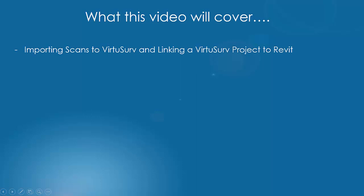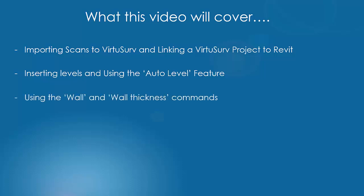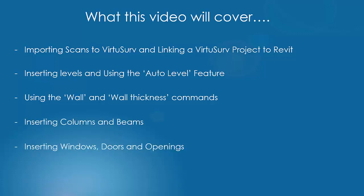In this video, what we're going to look at firstly is importing scans into VirtuSurv and linking the VirtuSurv project with Revit. We're then going to look at inserting levels and using the auto level feature. We're going to look at using the wall and wall thickness commands, inserting columns and beams, inserting windows, doors and openings, and then inserting model lines and construction points.